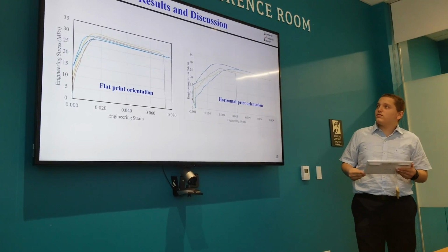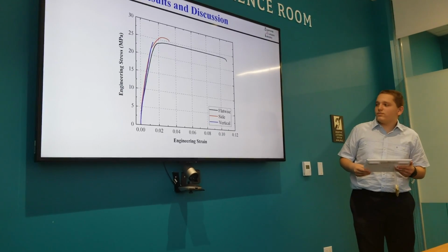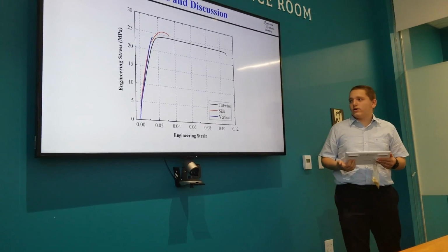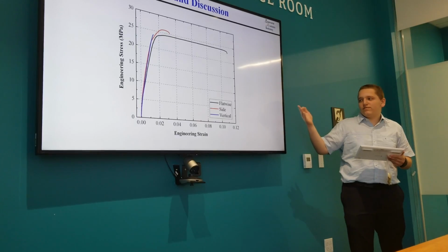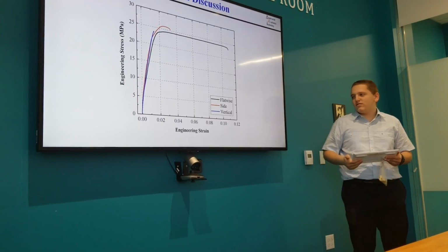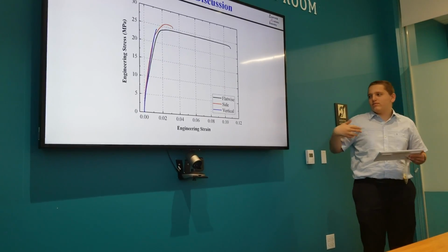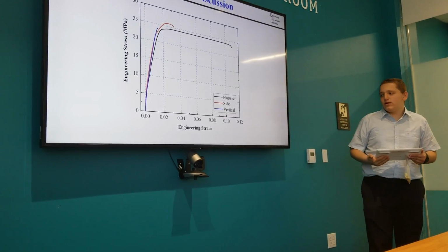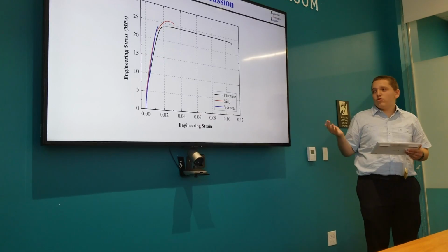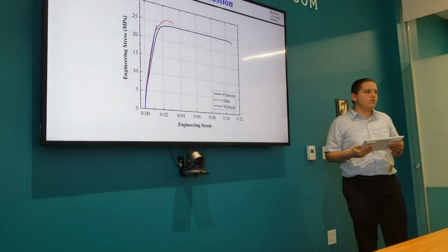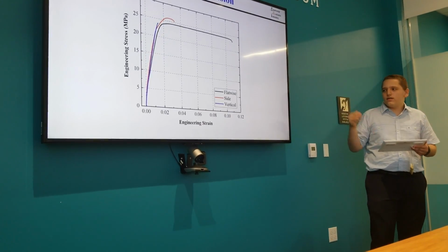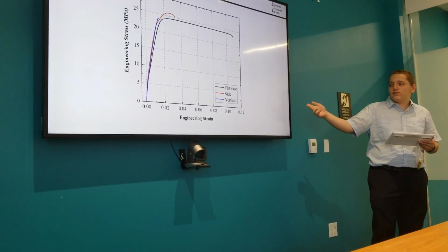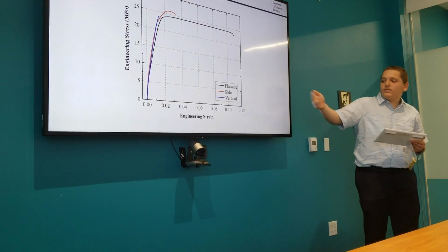So we use this. This was based on a thesis I researched. This is what we decided to use, which shows how the flat and the side are oriented differently. It's the same sample, but we call it horizontal. Flat, horizontal, and vertical. Overall, this showed that the flatly oriented printed samples had more strain than the other ones, and vertically printed ones had the least strain.